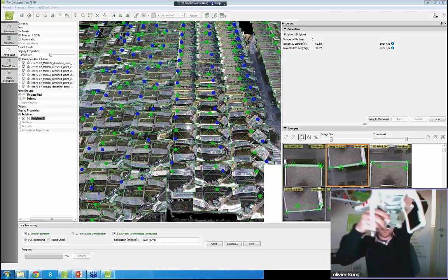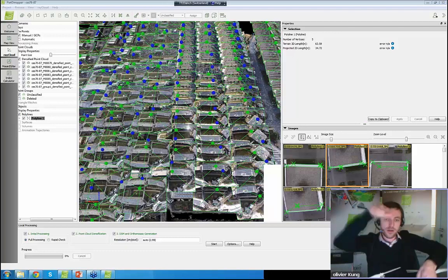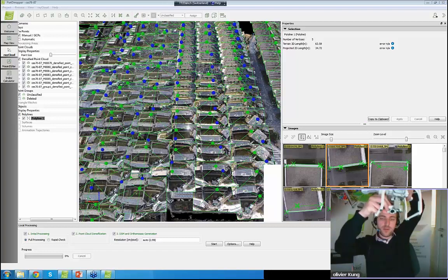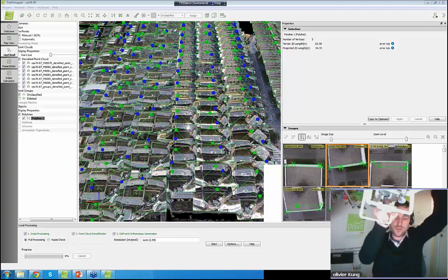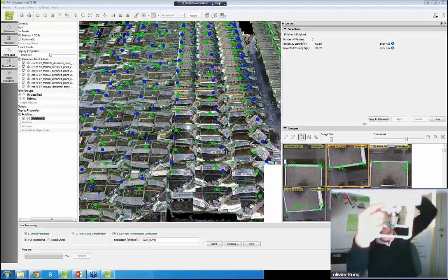And we would recommend, if you do a double grid flight on the same area, something that can improve the result quite a bit is to fly with the camera not at 90 degrees, but at, let's say, 60 degrees. By flying at 60 degrees, the drone is going to take the images in one direction and the other direction at 60 degrees, so you'll have more texture on the facade.